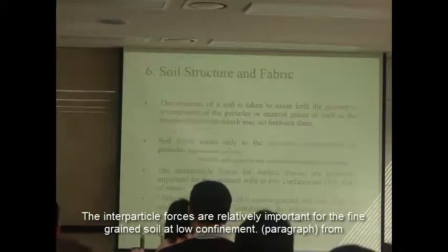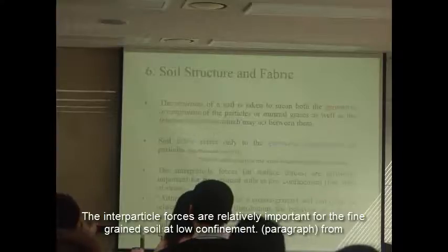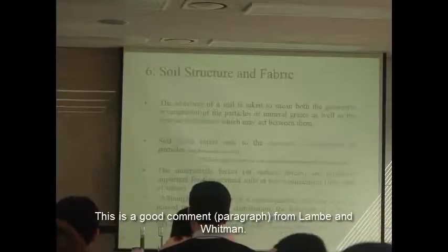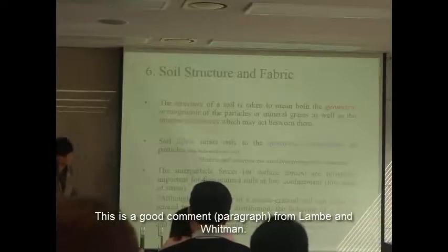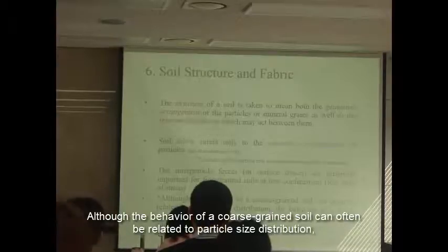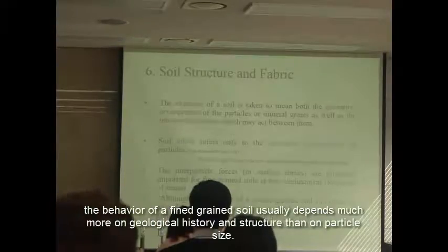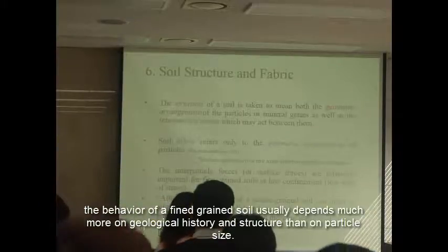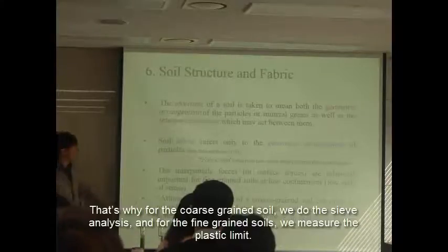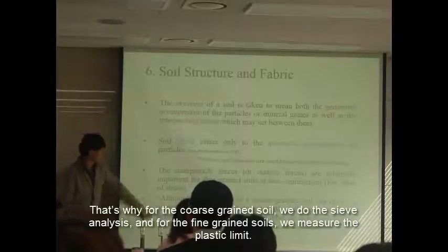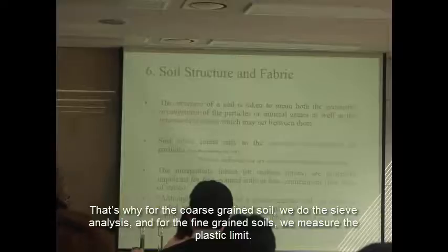Interparticle forces are relatively important for fine-grained soil at low confinement. Here is a good paragraph from Lambe and Whitman: although the behavior of coarse-grained soil can often be related to particle size distribution, the behavior of fine-grained soil usually depends much more on geological history and structure than on particle size. That's why for coarse-grained soil we do the sieve analysis, and for fine-grained soil we look at the plasticity.